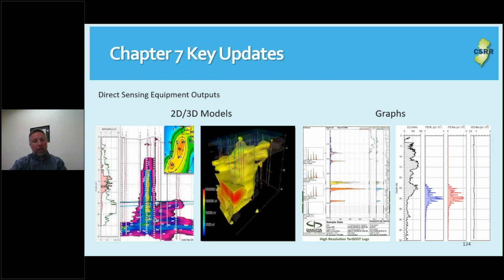You can do an ECD detector, which is an electron capture detector, which focuses on chlorinated solvents. And then at the same time, you can also do CPT, which is a cone penetrometer, and you can get some physical properties about your soil types. But just recognize that there's a lot of tooling that can go into this, and you have to understand the application, what compounds you're targeting, and then the overall approach for your project. Next slide.